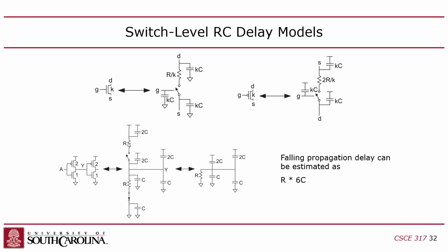But this one, this is the drain. The drain has a capacitor effectively on the output of the gate down to ground. So that's directly putting a capacitor on the output of the gate. Devastating for speed, right? You're basically putting a low-pass filter on the output of that gate, but just a consequence of transistors, no way around it.